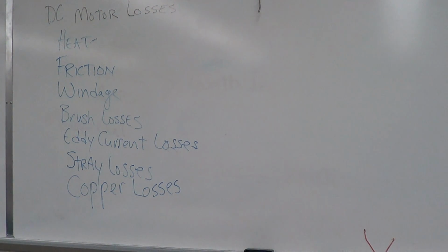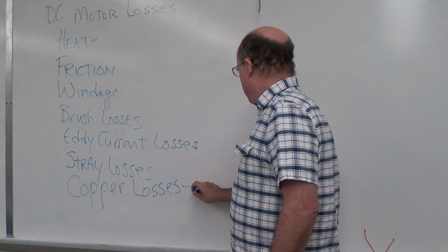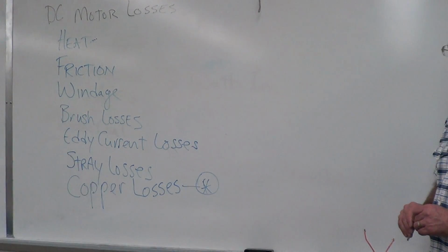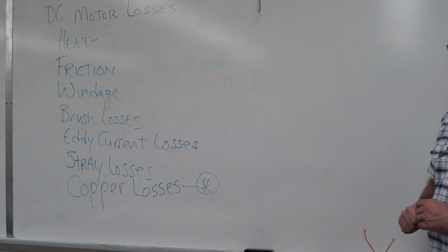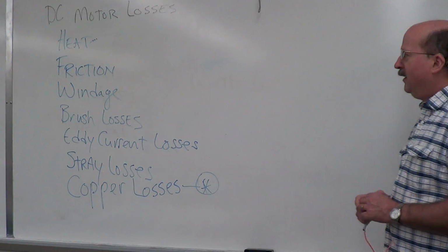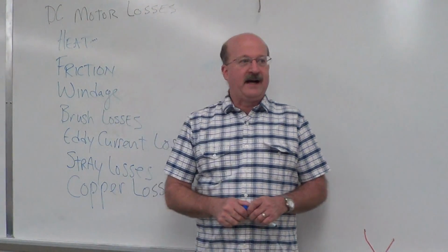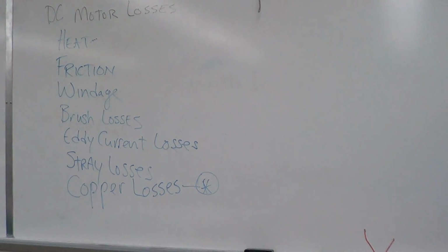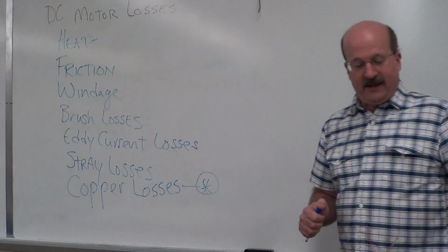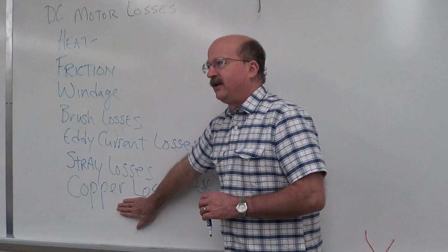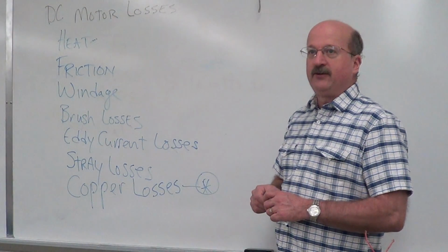We've got all those losses up there, and there's some of them that we can calculate. We can calculate our copper losses. All of our copper losses we can calculate. Friction losses, windage, you can fire up your motor and take your fan out, so you can measure the before and after with and without the fan. But basically what it boils down to is you have all of your copper losses that you can calculate and the contribution based on that.